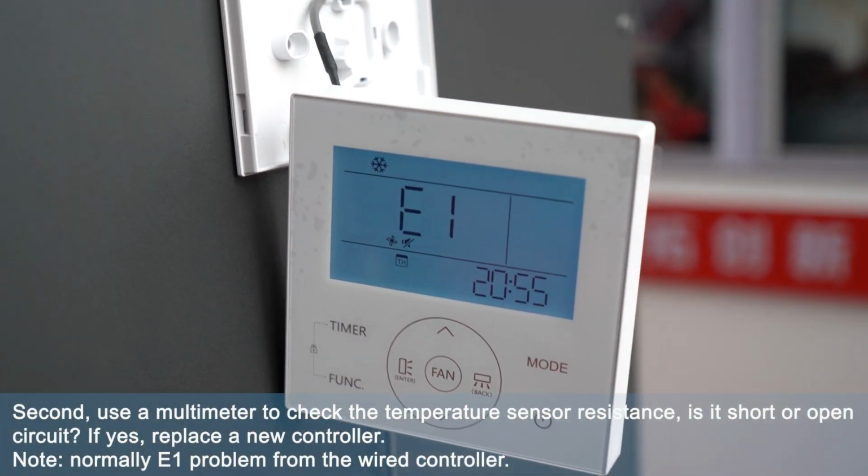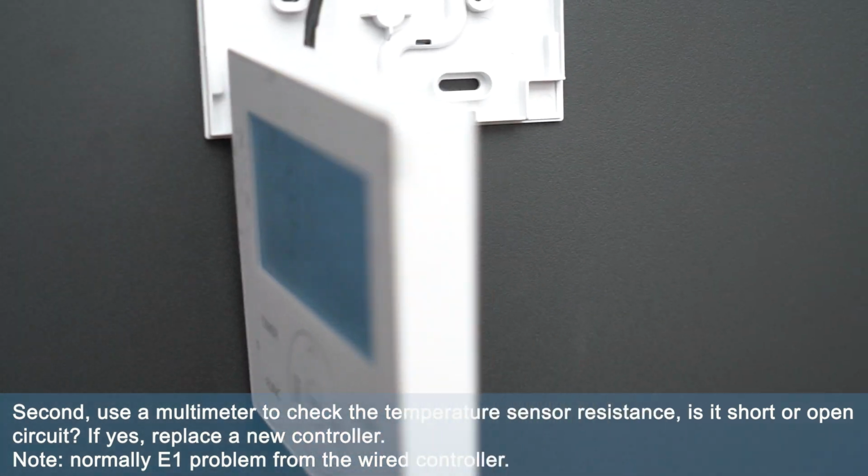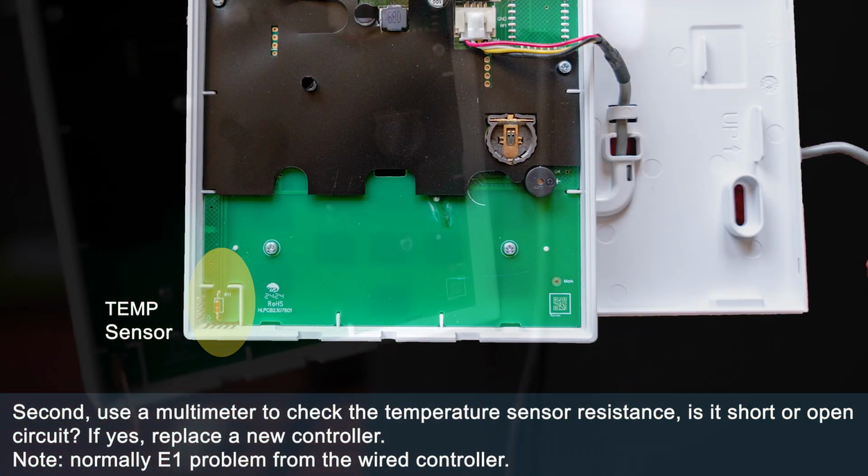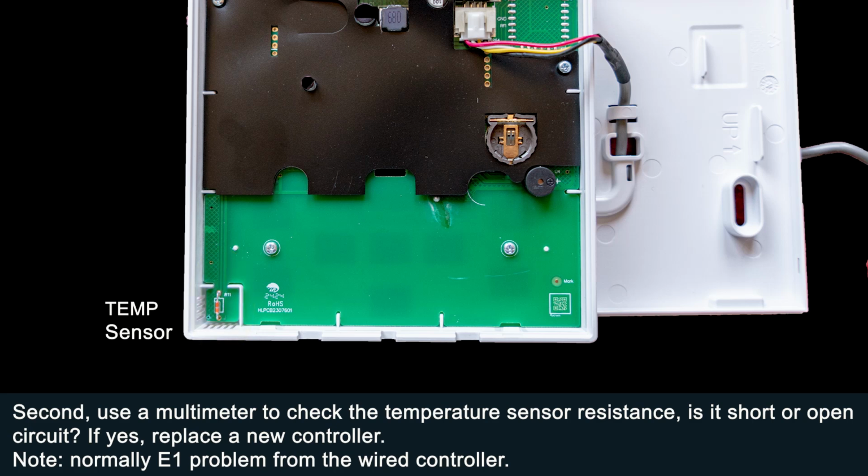Second, use a multimeter to check the temperature sensor resistance. Is it short or open circuit? If yes, replace with a new controller. Note, normally the E1 problem comes from the wired controller.